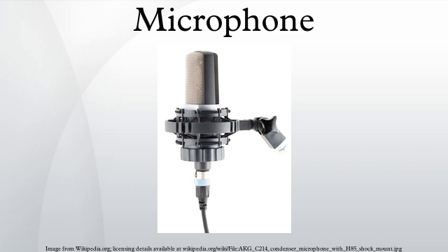A visible example of an optional accessory windscreen is the A2WS from Shure, one of which is fitted over each of the two Shure SM57 microphones used on the United States President's lectern. One disadvantage of polyurethane foam microphone covers is that they can deteriorate over time. Windscreens also tend to collect dirt and moisture in their open cells and must be cleaned to prevent high-frequency loss, bad odor and unhealthy conditions for the person using the microphone.